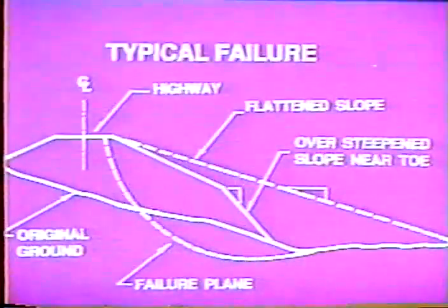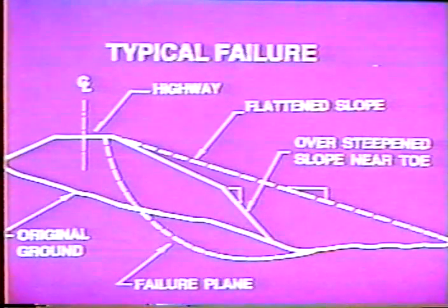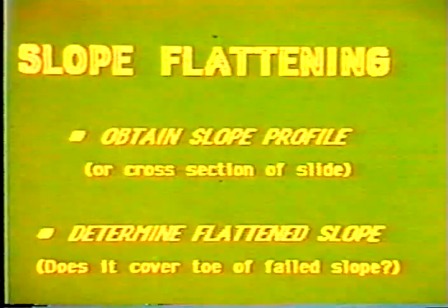That's just another view of that same slide, the toe there. Slope flattening also is an effective technique for over-steepened slopes near the toe. Perhaps the steepness there has been caused by erosion, or maybe it was constructed that way. But here again, simply flatten the slope out.